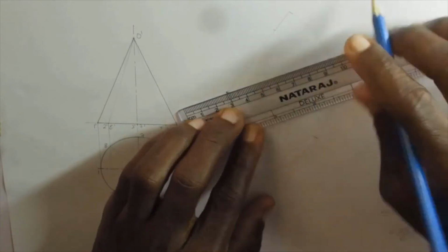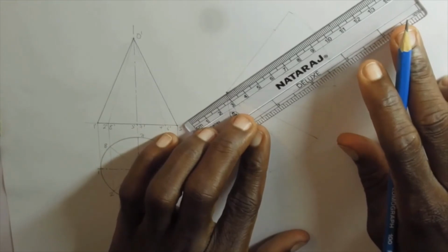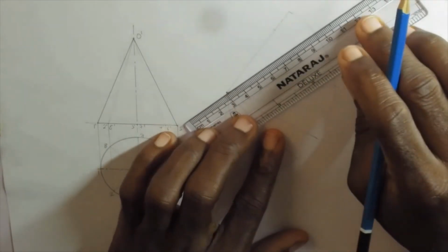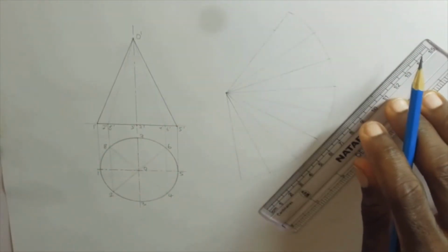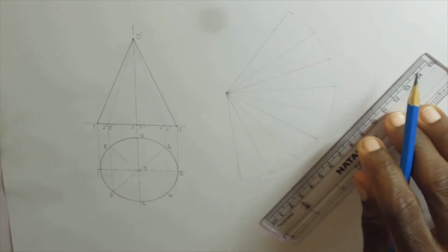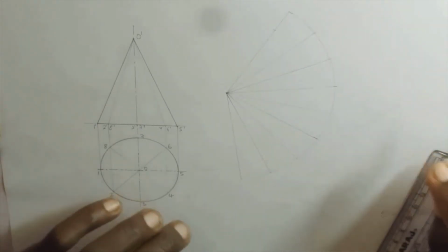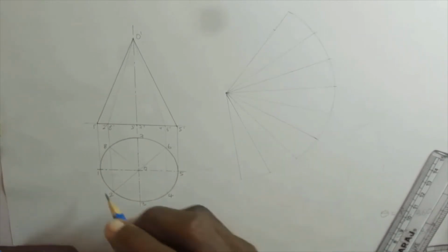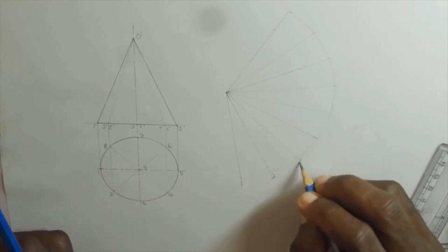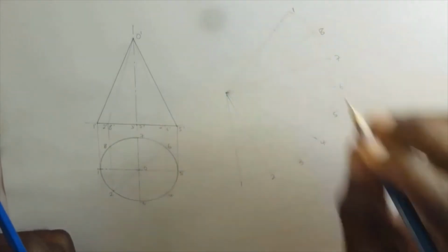After that, we need to add, let's say, the base circle, in case the base is closed. But before that, we have to label the points that we have obtained on the arc, and that depends on where we want to cut open the cone. So we can decide that we cut it at 1. In that case we have 1, then 2, 3, 4, 5, 6, 7, 8, and then we end at 1.